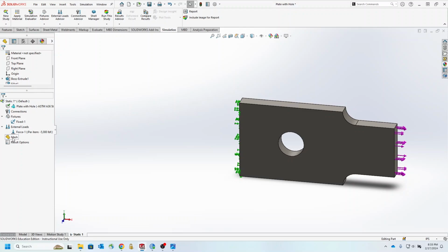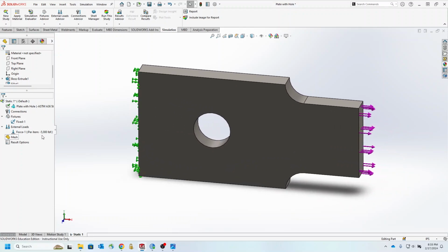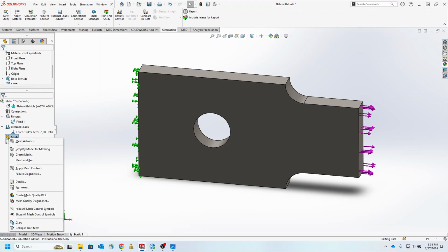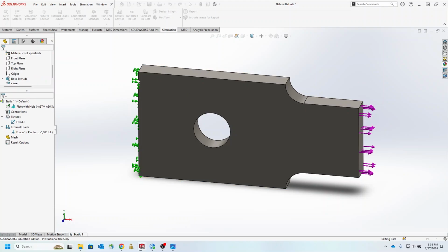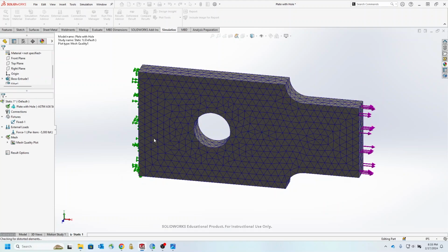When we create the mesh, you will have a better understanding of what my explanation and reasoning look like. In order to do the mesh, you are going to right click on the mesh and click this option, which is create mesh. And another window would pop up, which essentially would ask, what is the density of the mesh? Meaning how fine or how small those small parts should be. If I select, let's say here in the half range, I would show you what it looks like. So if I hit OK, SolidWorks would start creating the mesh. So it would freeze for a second.